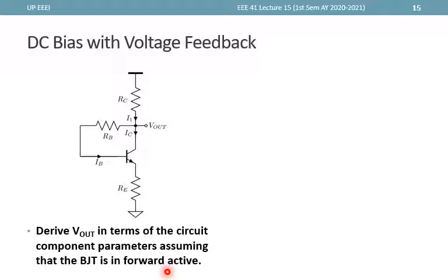And why is that so? We are actually sure that this circuit right here will be in forward active regardless of the values of the resistances, as long as the supply voltage is large enough. Now, how come the circuit is able to achieve that? So note that for forward active we want VCE greater than VCE sat, and that VCE appears at these two terminals.